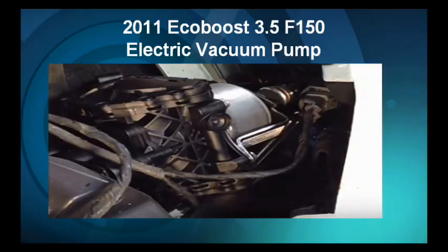Now Ford will either utilize this mechanical pump for additional vacuum for the brake booster, or it may use an electric pump that may be found behind the left front headlight, such in the cases of Ford F-150. So either one of these may be utilized to provide additional vacuum for brake booster operation.